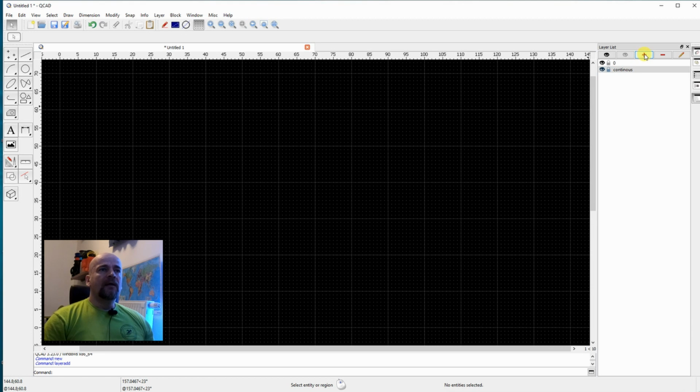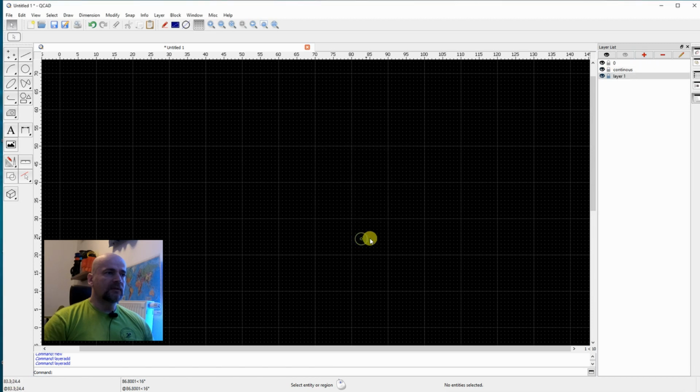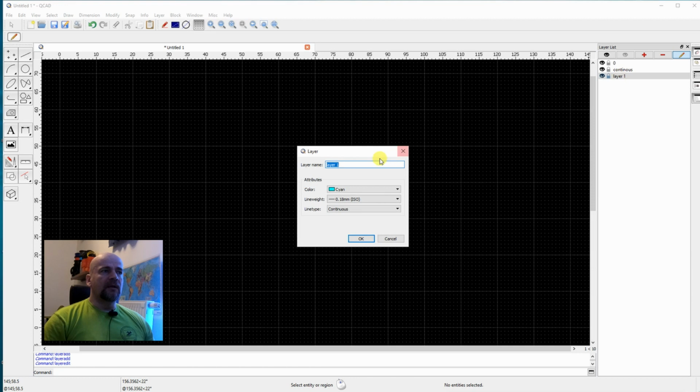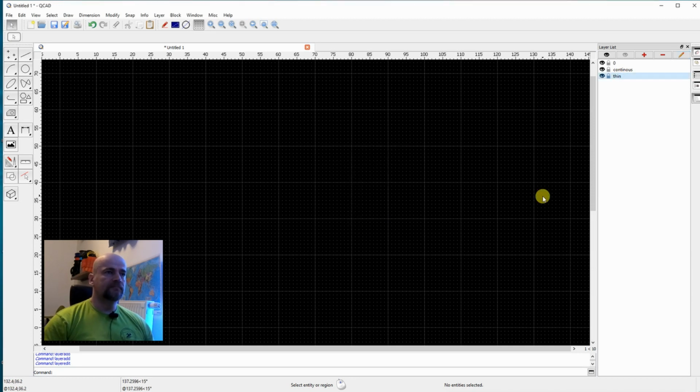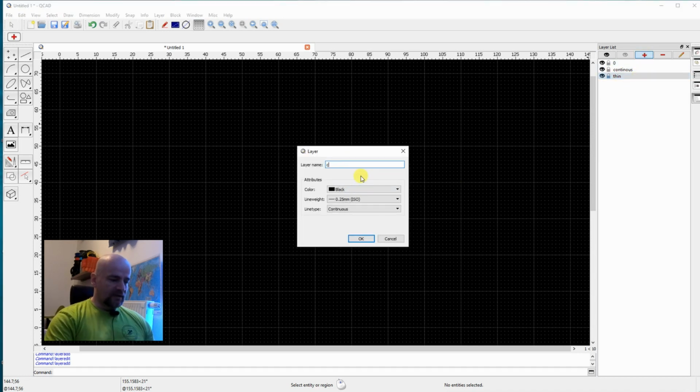Okay. Then I will need a thin line. Let's see. Okay, continuous, and this one be cyan. Okay, I didn't get the name. Okay, and I will add a center line.